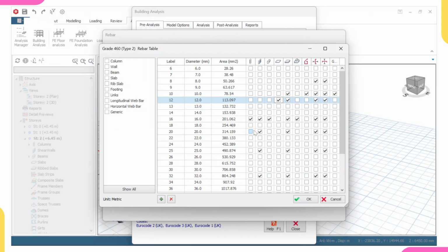If I'm carrying out a duplex design and I have Y20 in my reinforcement, and I submit my structural detailing or my BOQ, the client might not even look at my work, because he's seeing Y20, saying but all the duplexes are Y16. So that's why I don't normally like checking Y20. I'll check only Y16 for the column and for the beam. Then we don't have a shear wall. In terms of the slab, I'll check only Y12.